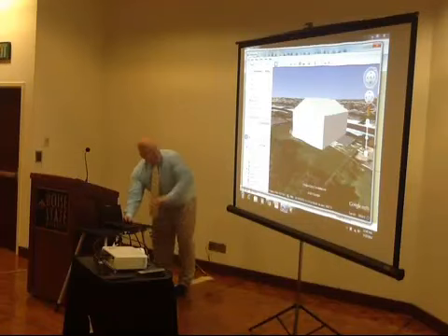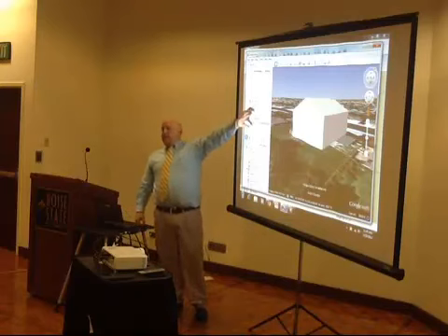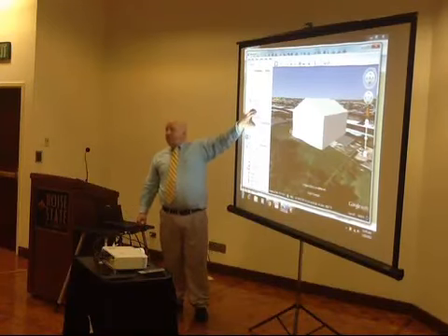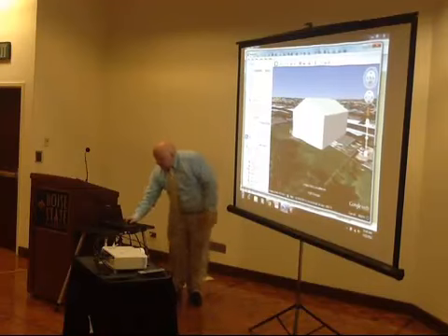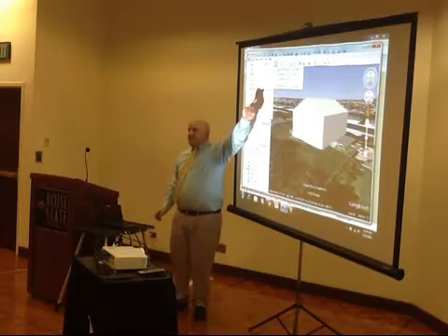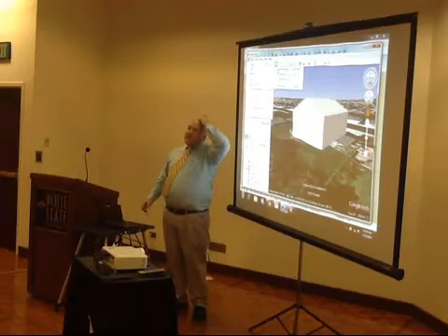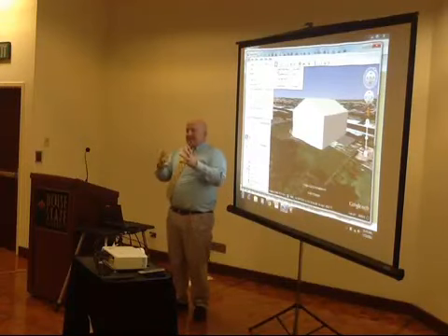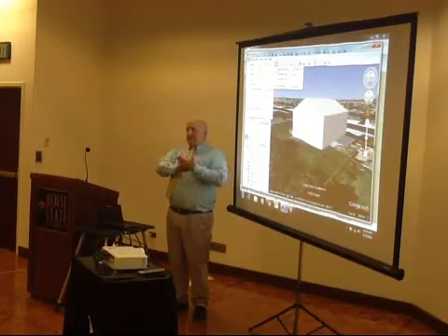Once you've loaded it into Google Earth, this checkbox over here is checked as a temporary place. With that checked, if we go up to the File menu and say Save, then Save to My Places is one of the options. So it looks like the easiest way to do it is to build it in SketchUp, preview it in Google Earth, then save it to My Places.